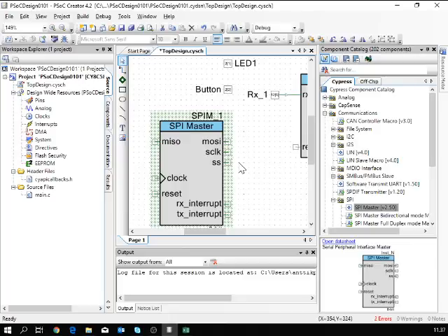You would need that pin, of course. Clock. Read the data sheet and see how fast your clock can be. That device, you can use it up to, was it 1 mega samples per second. So you can have a 60 megahertz clock there. But check the datasheet. Don't believe me. I make mistakes.